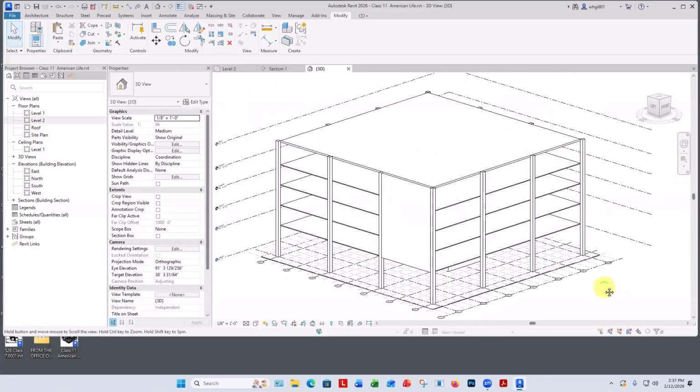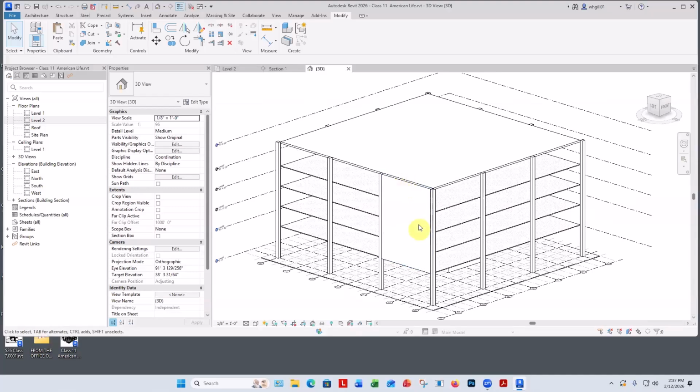So what I'm going to do here briefly is get this panel just right in terms of where the bottom is, where the top is, where the glazing is, that is all correct. And then we can just copy that as a group to all these other individual locations around the building, since they're all exactly the same. I mean, you couldn't pick a better sort of CAD efficiency drawing than this one right here.